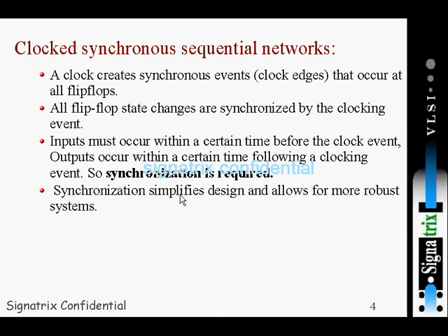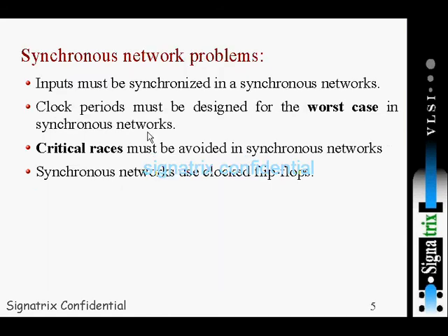Synchronization simplifies design and allows for more robust systems. So in synchronous design, why are you going for synchronization? Your design is much more robust and controllability is more. Your design is simple, it is very simple to design a synchronous circuit, because we know we have to work with respect to one global signal, that is the clock. By seeing that clock signal only, all the events should occur. So it is very easy to design synchronous circuits.